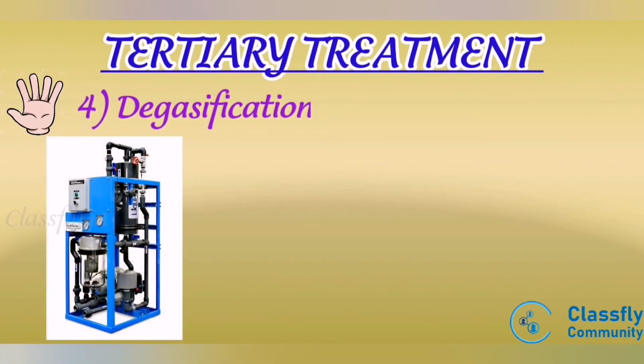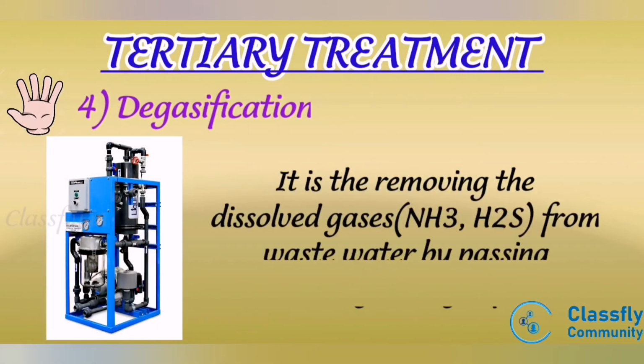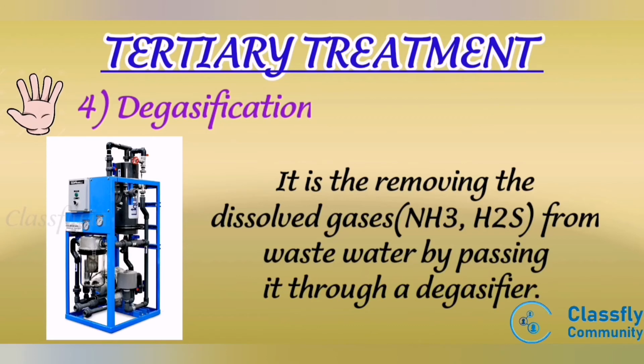Fourth method is degasification. It is the process of removing dissolved gases like ammonia and hydrogen sulfide from the wastewater by passing it through a degasifier. The solubility of gases decreases with increasing temperature of the liquid. This concept is used to remove the dissolved gases in wastewater.